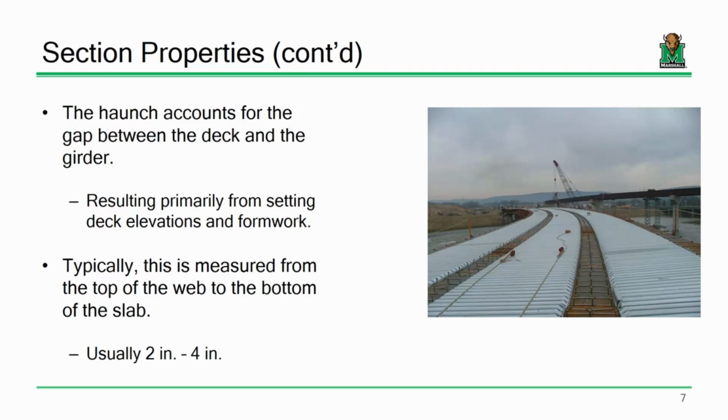Okay. One thing to keep in mind is something I've been pretty fast and loose on. We will actually spend a fair amount of time this semester looking at just the studs themselves and figuring out how many studs need to go on the beams and in what spacing. The only point I'll make is if you look at a steel beam in a building as opposed to a steel beam in a bridge, there is an ocean of studs on bridge beams, okay? And the reason can be summed up in one simple word: fatigue, okay?